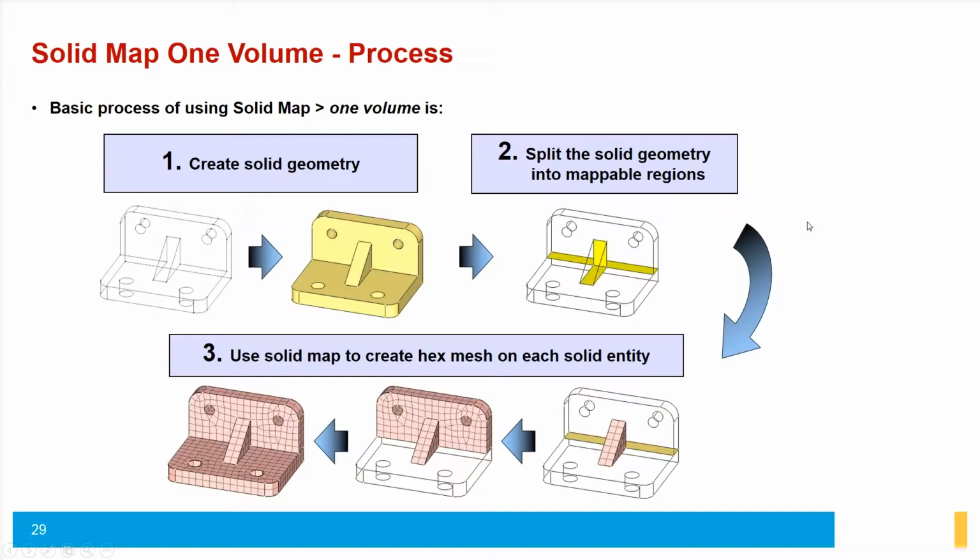But once you work on a complicated part like this one, where you have all these different things going on, then it becomes a challenge because you don't know where the source face is, you don't know where the destination face is, and you kind of have to divide it into pieces where you can have a source face and a destination face. So in this case, they grab this geometry, and as you can see by this third one here, you partition it, you divide it into these, and hopefully you guys can see my mouse, right? I don't know if you guys can see my mouse.